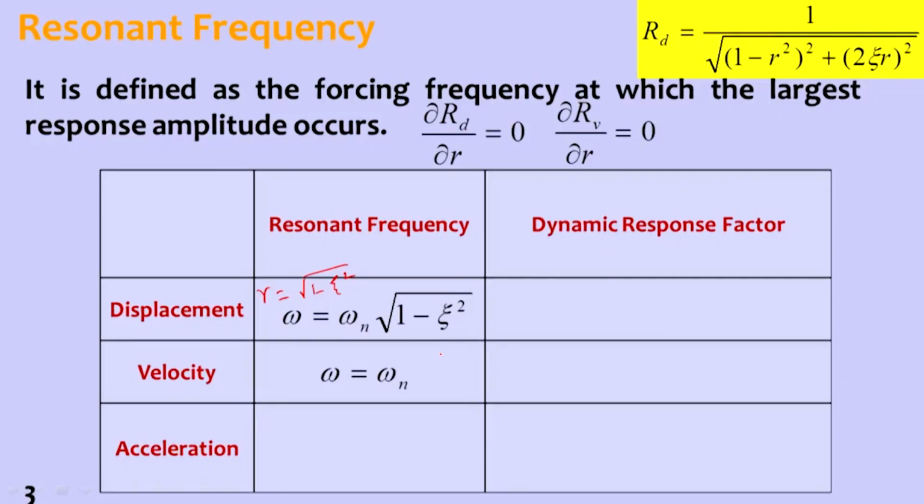That resonating condition occurs for velocity, not for displacement or acceleration. And in the special case when no damping is there, all three become equal.